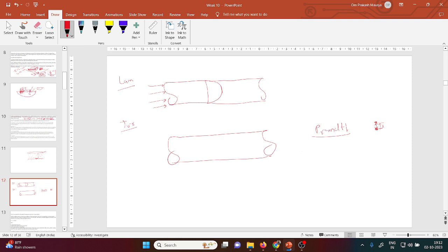As per this concept, Prandtl was telling that the turbulent flow, let's say this is the magnitude of the turbulent flow, has two things. If we try to write it mathematically in a quantitative way, we can write the average component and the fluctuation component. If we combine these, it gives the turbulent velocity. So Prandtl tried to quantify this using the mixing length concept.